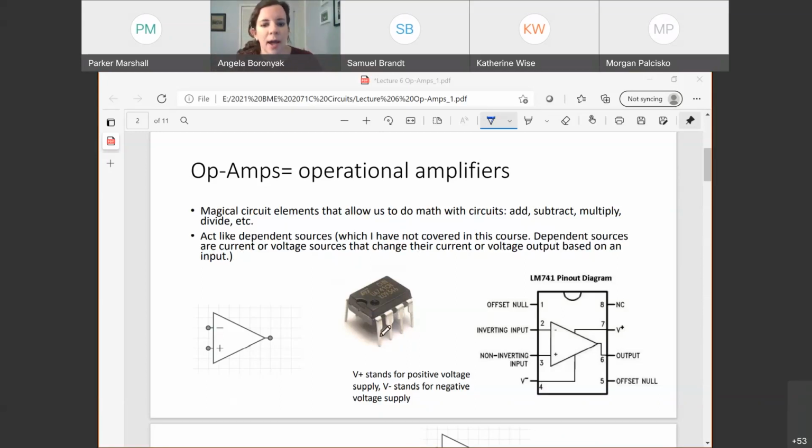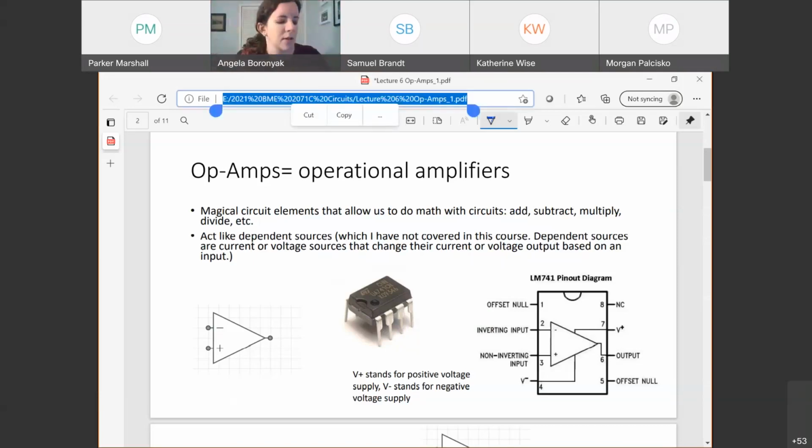What do op amps look like? I call them little 8-legged spiders, or they kind of look like some sort of Star Wars robot. In real life, this is one. Again, circuit elements are tiny in general, right? But it's got 4 little metal legs on one side, 4 little legs on the other. And in a breadboard, we tend to put them what's called across the gap in your breadboard, from where it goes from 5 pins on one side to 5 pins on the other.